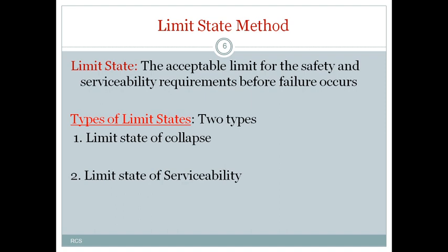The actual definition of limit state as per IS 456-2000 is the acceptable limit for the safety and serviceability requirements before failure of a structure, or before failure occurs in the structure. So what do you mean by this? If you consider any material or structural element, and if you apply a load over it, it is going to fail at a particular load.